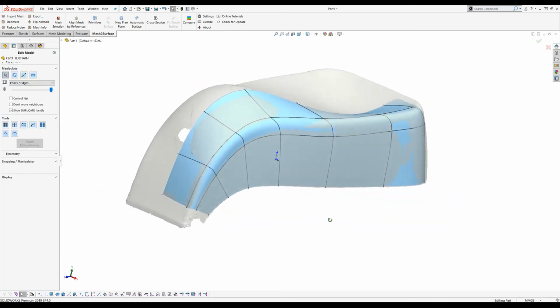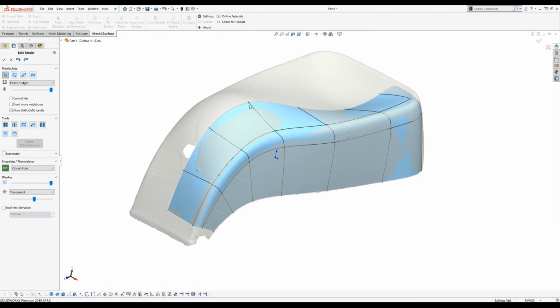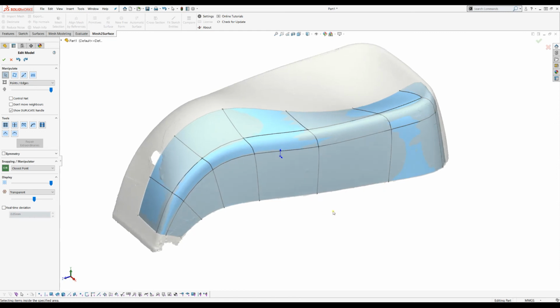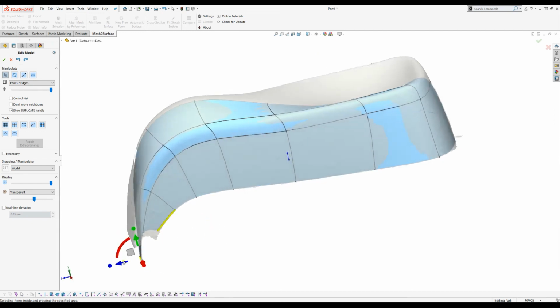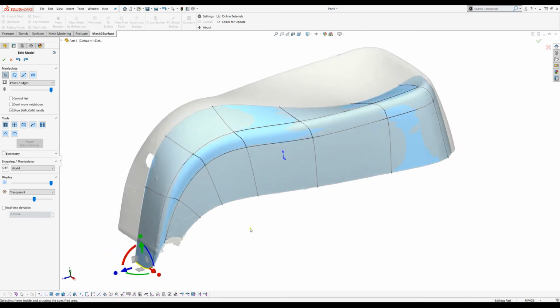What happened now is that actually I displaced this and it's not on the mesh, so I probably need to move. If something happens and you turn on and off the snapping mode, which is possible, for example, I can just turn this off and select this, and then with the manipulator I can just drag outside of the mesh. This is also possible, so you can adjust something that is not belonging to the mesh. You can always switch between the snapping mode and the manipulator mode.